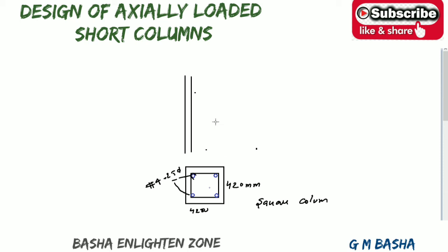These are the dia bars, and actually the bars we have to show with the blue sketch, with dia around 25 mm. If you cut this section and see these bars, or see from the front view, they will be visible like this only. There will be only 2 bars visible.